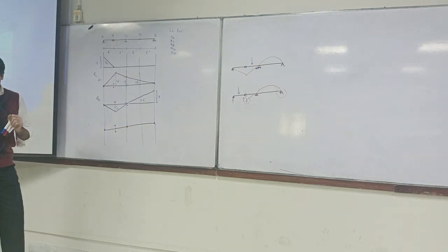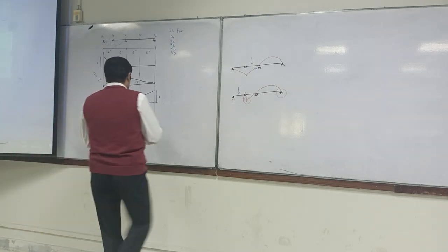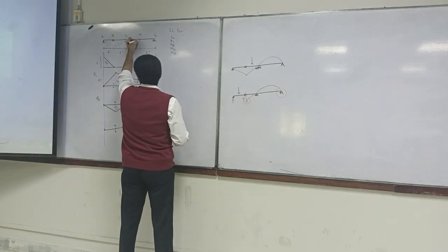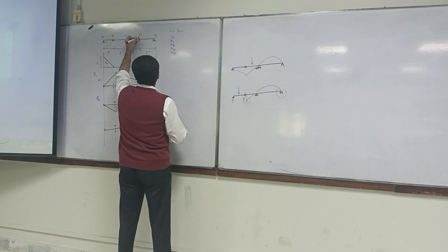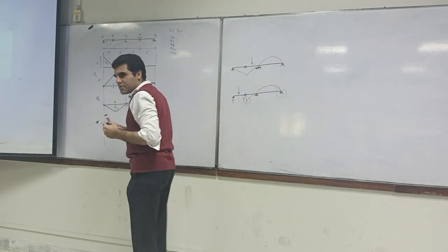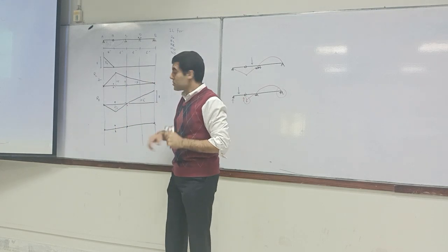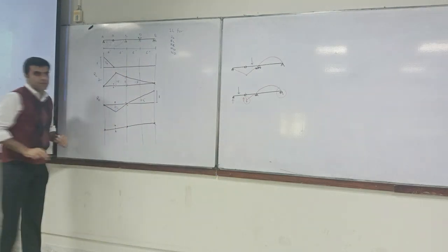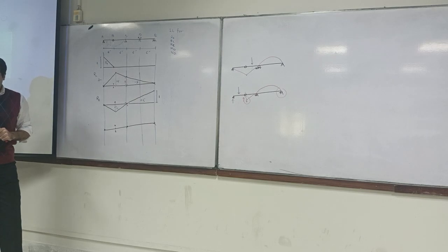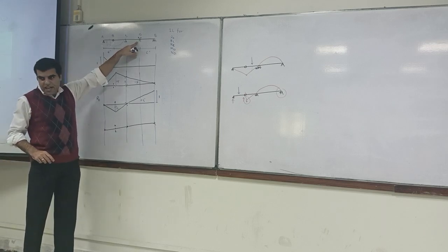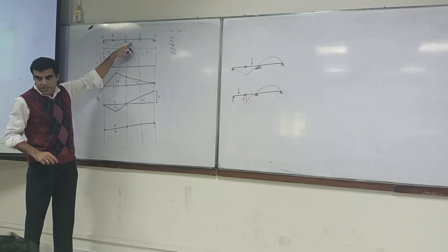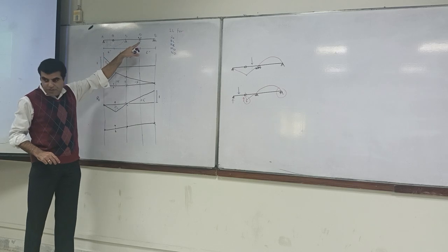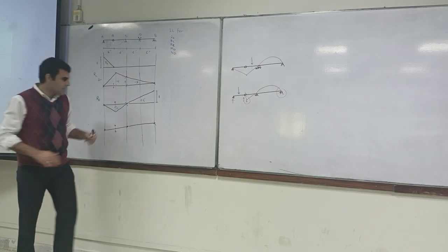If I've got these moments applied, what does it tell us? If I've got a moment like this applied, then where is our tension? At the bottom. So I should better move it down.